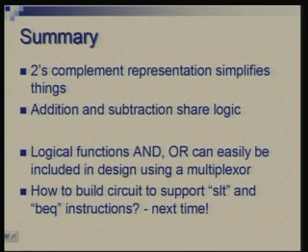Okay. So, to summarize what we have done today, we have looked at 2's complement representation for signed numbers, and seen that it first of all brings a unique representation for 0, which was the problem in other representations, and secondly it simplifies our mechanism for performing operations. So, the circuit is simpler, we can ignore the sign while we are working with it.